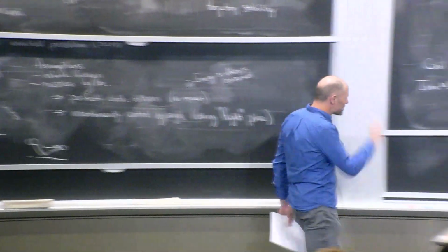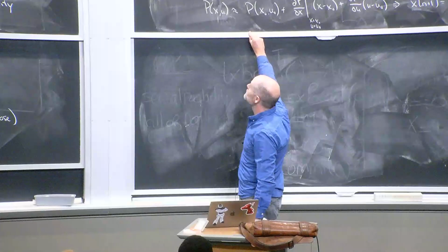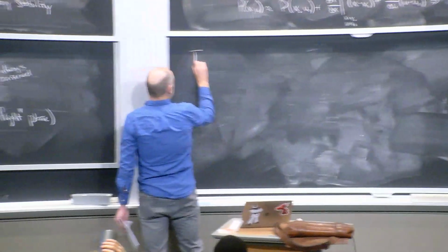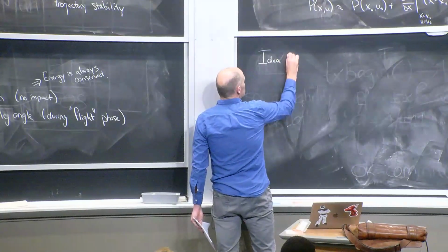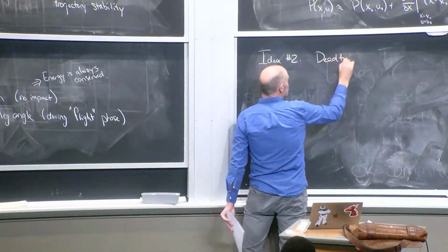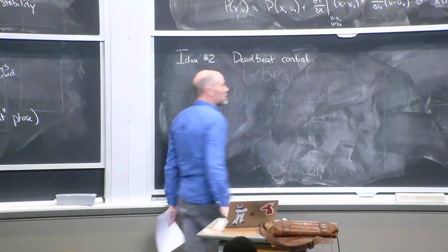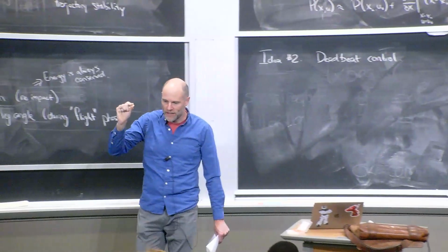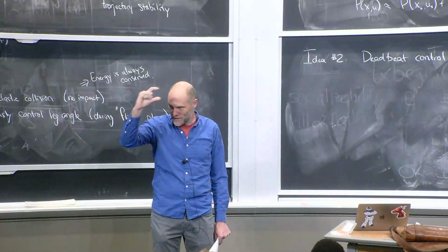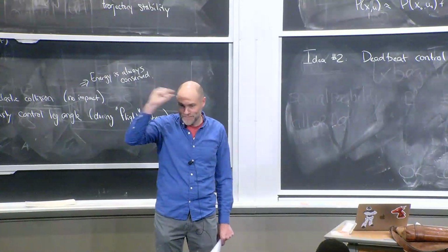Turns out that for SLIP you can do better, not better than LQR. LQR is optimal for the quadratic regulator objective, but there's another natural objective for the SLIP, which is the deadbeat controller. So the LQR says, I would like to penalize over multiple steps the quadratic error distance from my desired fixed point and the quadratic effort I put in.